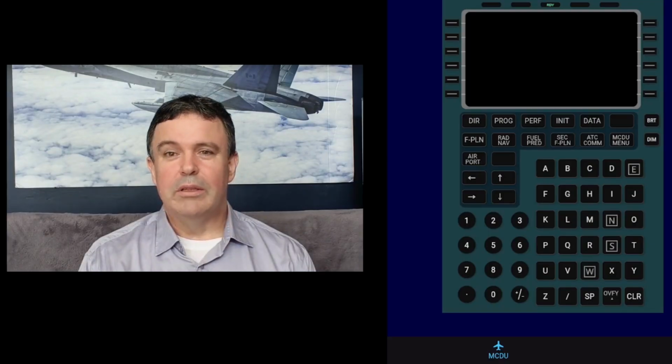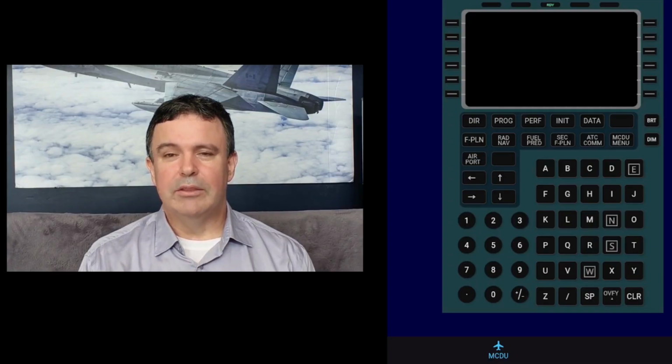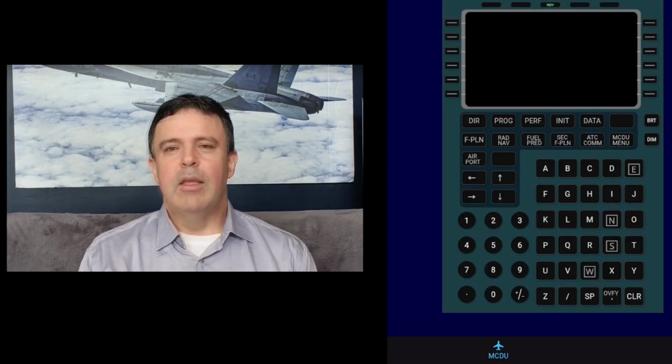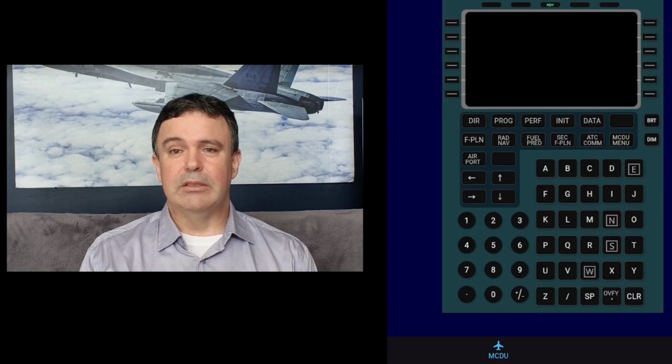Now, as you can see, when the device is first loaded, the power is not on yet. So the ready light on the top wall of Inertial is lit up. That indicates the power is off but available. To switch it on, all we need to do is press the right key over on the right hand side of the MCDU. This opens the MCDU to whatever page was previously stored in memory.